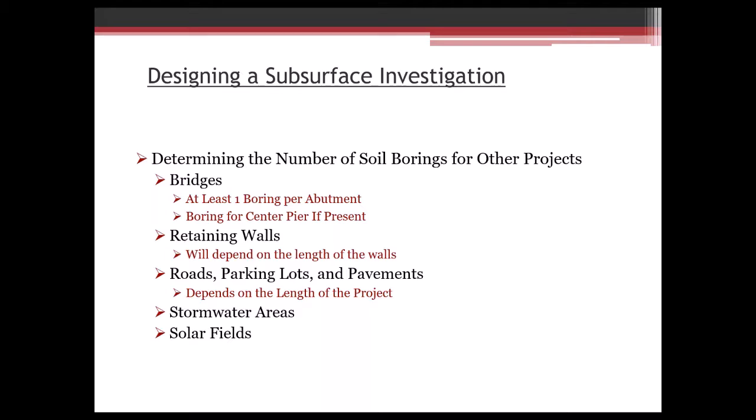Roads, parking lots, and pavements are also another similar thing that we struggle with a little bit, determining the total number of borings for, because the projects can vary from relatively small parking lots where maybe only 1 or 2 borings are needed to long stretches of road where you may be doing several borings per mile or even only a few borings per mile.